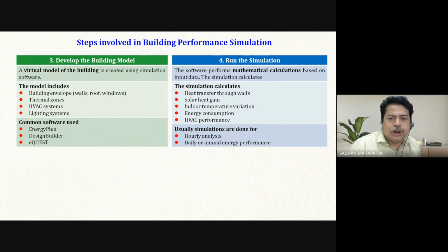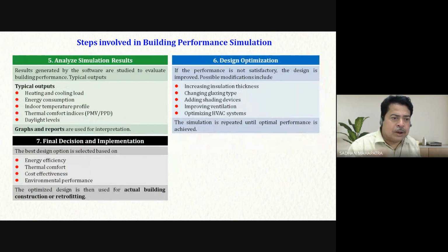You run the simulation, and the simulation will calculate the heat transfer through the walls, solar heat gain, indoor temperature variation, energy consumption, and HVAC performance. This can be hourly analysis, daily analysis, or annual energy performance. Analyze the simulation results. Typical output would be heating or cooling load demand, energy consumption, indoor temperature profile, or